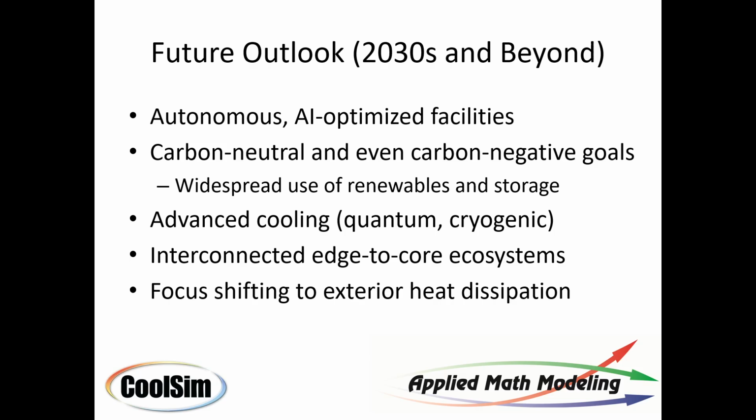And the focus shifting for us here, our job is to help predict heat transfer, in particular of these devices. Exterior. We have been fairly efficient getting the heat out of the data center over the years, and now it's outside. And the issue of how these heat exchangers outside of the building, typically on the rooftop or beside the building, behave under prevailing weather and wind conditions becomes quite important.